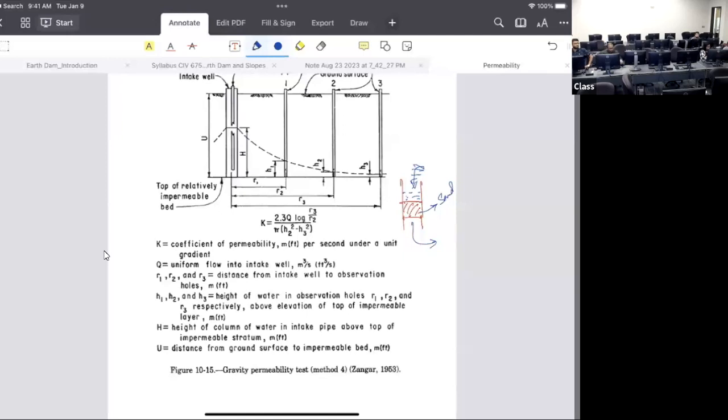So basically what's going to happen is you will see the water level difference between time T1 and time T2. Whatever the time difference you have, in between you'll see how much the water level has changed, right? That's it. Based on that, you can calculate the permeability in the clay, not in the sand. In the sand, you have to keep a constant height, no matter what. Clear? That's why we need the falling head and the constant head.